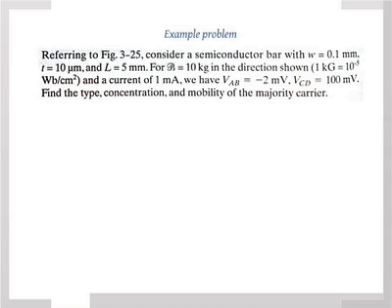Okay, let's get started. So how would you address this? The first question is what is the type of the semiconductor? Is it p-type, n-type, intrinsic? N-type. Why? Because V_AB is negative. It's okay if you don't know. That's fine. It's n-type. Why? Because V_AB is negative.